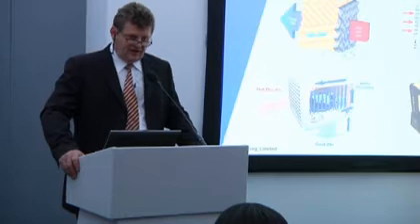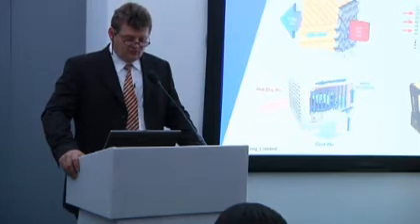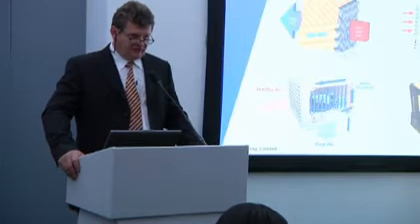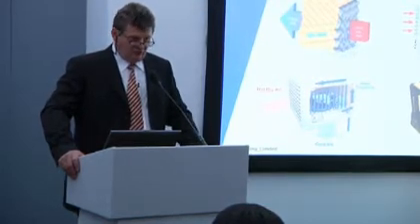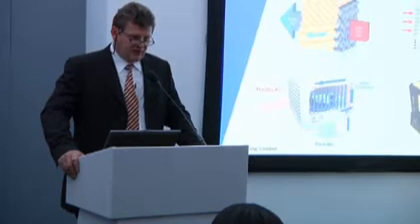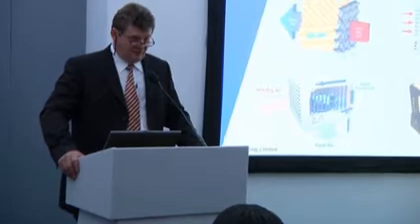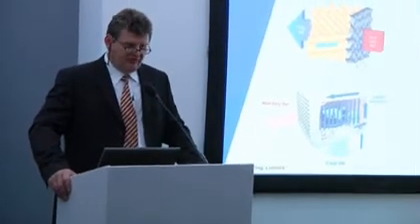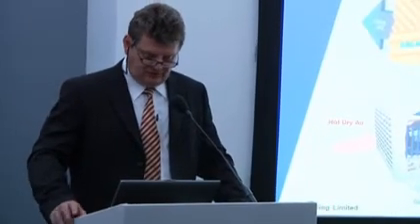The heat required to change the water from a liquid to a gas comes from the air, which then cools down. And we incorporate these wetted filter pads into a thing called an evaporative cooler, which is four wetted filter pads with a water circulation system and a fan to move the air around. And we build this into a device called a CREC, a computer room evaporative cooler.